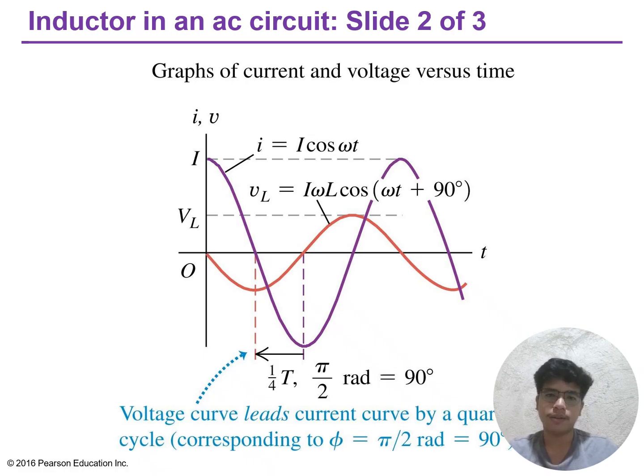The practical consequence is that in circuits with inductors, you cannot simply multiply instantaneous voltage and current to find power. The phase difference means that energy oscillates between the source and the magnetic field rather than being dissipated, a phenomenon we'll explore in detail when discussing AC power.